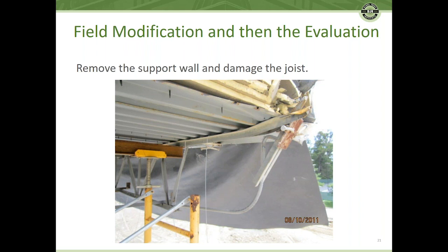The good thing here is that they shored up the joist. You can see the jack there, and it shored up the joist, and so there's some opportunity to fix it, or perhaps just get a new joist. But you can see quite a bit of damage was done.